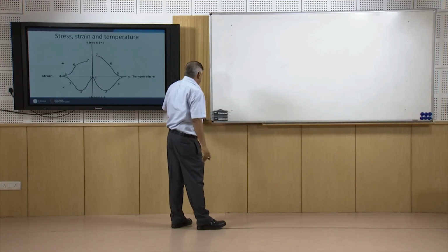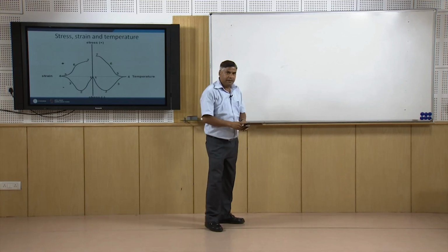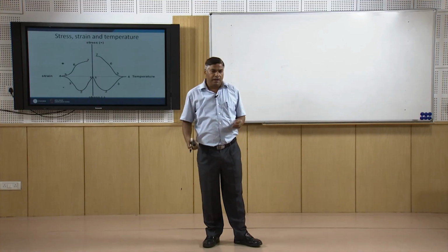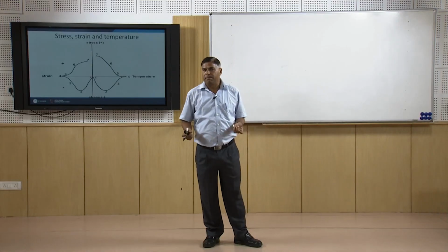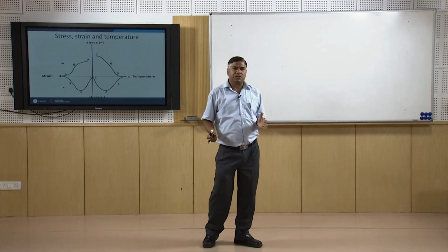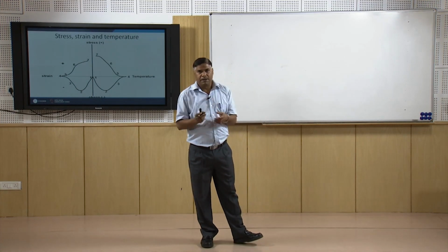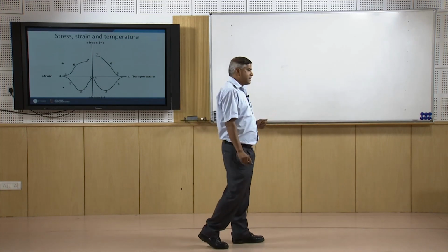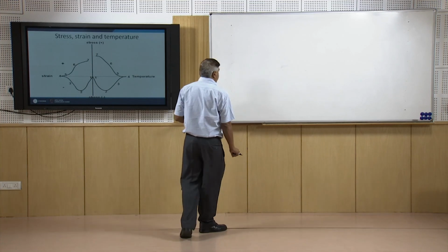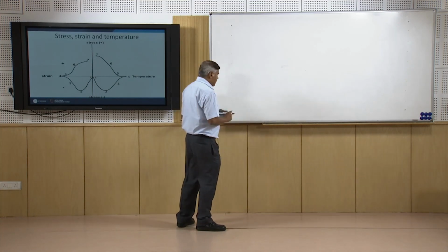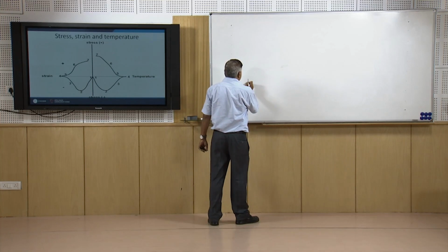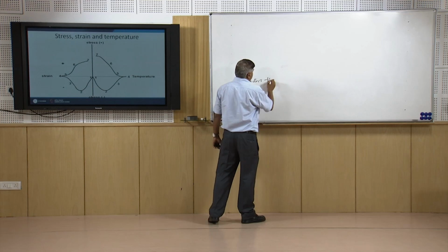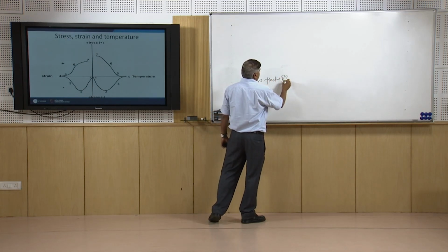So, what we have seen is that the tensile residual stresses basically develop along the weld center line, and when transverse shrinkage takes place due to the shrinkage of the weld metal, if the plates are kept under very restrained conditions, that also develops tensile residual stresses in the weld. So, now we will see how these factors are affecting the residual stresses.